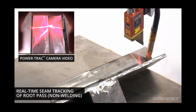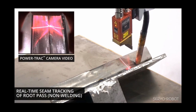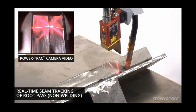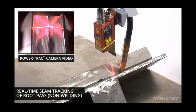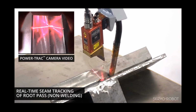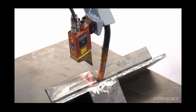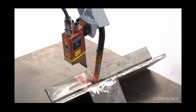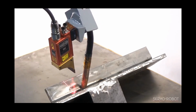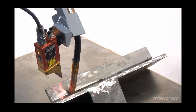This example shows a standard seam tracking product from Servo Robot that is used in welding. This system uses a laser line camera that determines the position of the weld seam. The remote camera system uses the RSI open interface to tell the robot whether to offset right or left to stay in the seam. This enables the robot to achieve good process welds regardless of whether the part is properly positioned or warped.